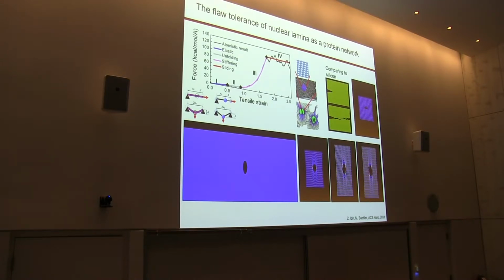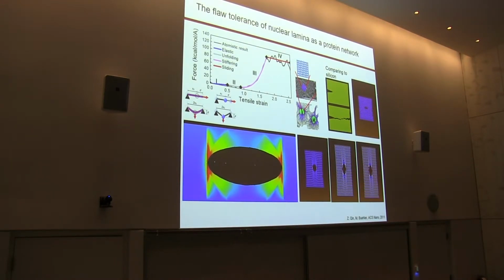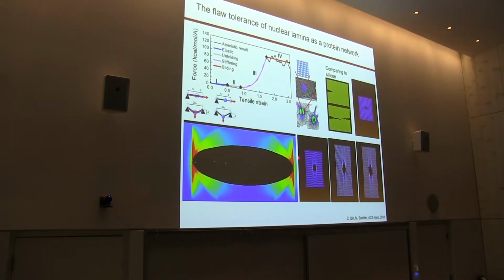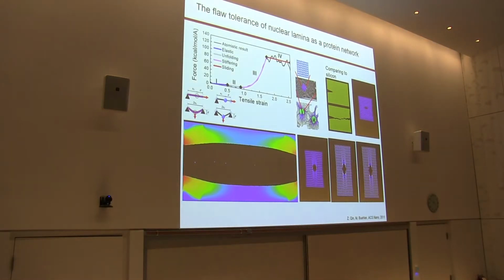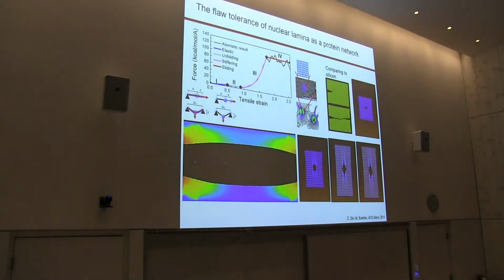So it behaves more like a rubber. If you have a balloon and then you make a crack, it will break because of the crack propagation. But here we can actually see a movie of how the crack might break for this nonlinear material, and also we can see the shock wave coming from the crack tip. That's very difficult for experiment to directly capture because the speed of the crack propagation is almost similar to the speed of sound propagation. But by using this simulation, we can do a lot of studies related to those dynamic crack propagation.